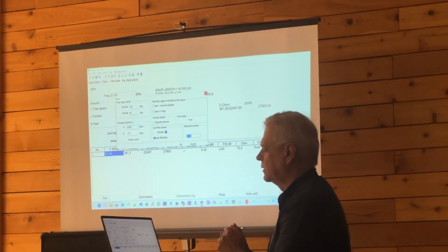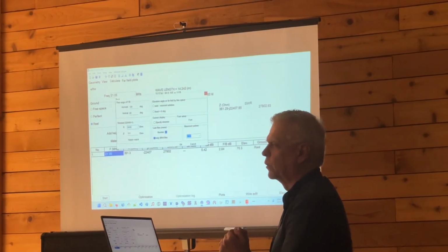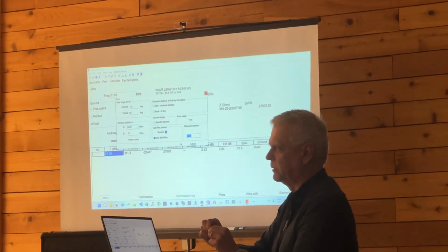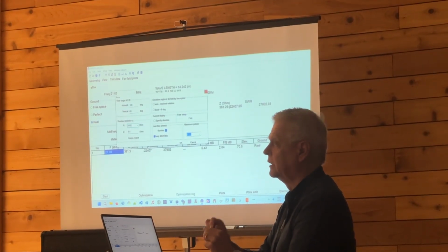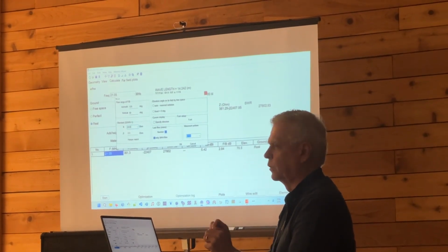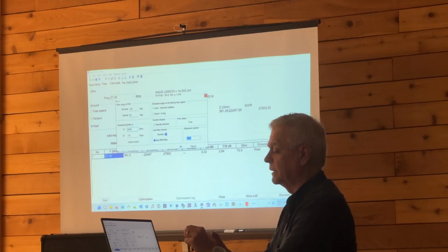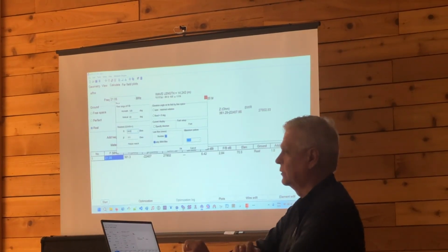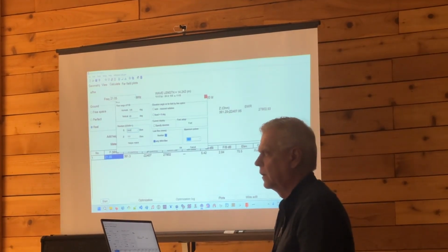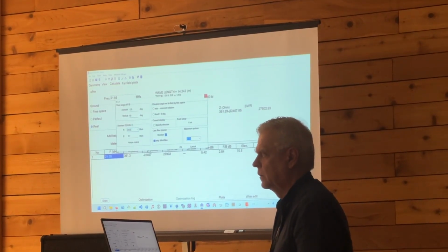Again, just to restate, we're changing this to 2450 ohms because the input impedance of this wire that's going to be radiating is going to be 2450, due to the 49-to-1 transformer. Remember, the 49-to-1 transformer is going to get us down to 50 ohms, and that's going to be our coax. So we're expressing the impedance of the feed point here.